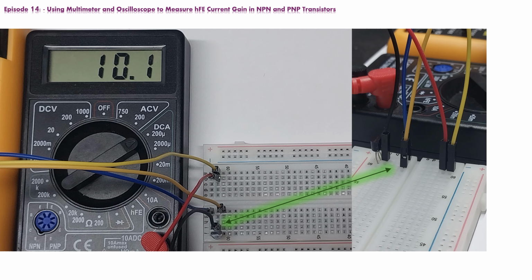All that is left to do is to verify absence of any small signal by using an oscilloscope. We will attach oscilloscope probes between base and emitter terminal. This will give us the shape of the voltage signal going into the base terminal of the transistor. So, our new setup looks like this. We can observe that the voltage shape on the oscilloscope display is a straight line, so, there is no small input signal present. We have verified that this is a correct measurement of the hFE parameter.